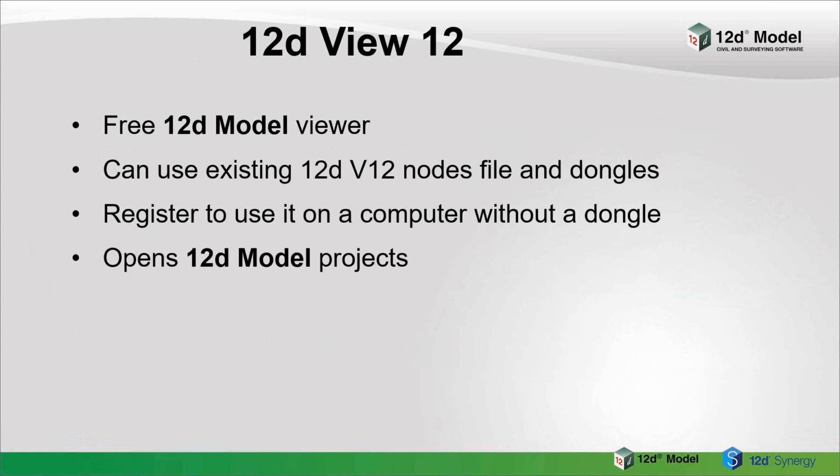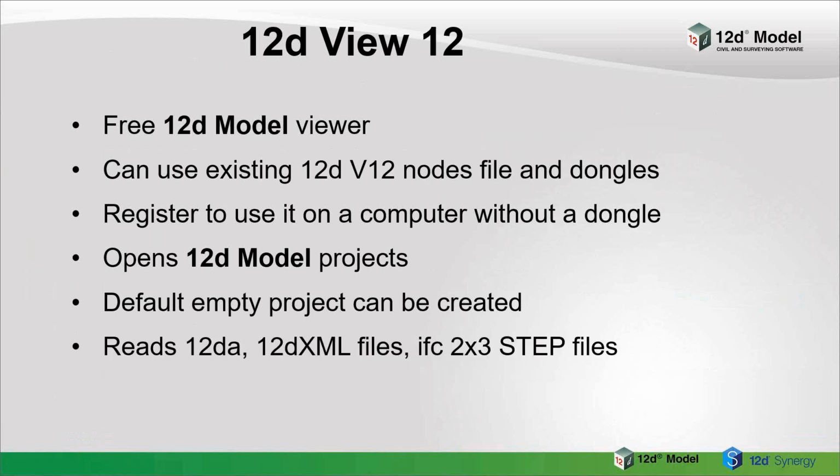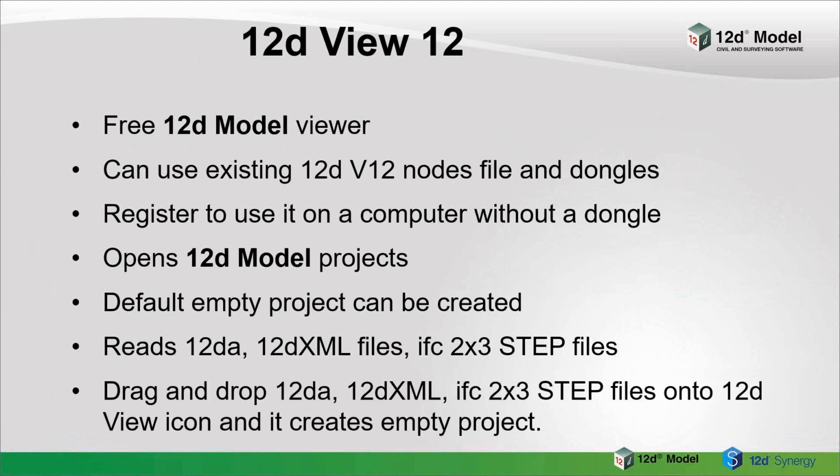It opens 12D model projects, but if you haven't had the latest C1M, you don't realise you can also create an empty project, so we can also read some data, not just 12D model projects, but we can actually read in the 12DA files, 12D XML files, and also IFC 2x3 step files. So that all can be done in the actual viewer, which is free of charge. And those particular things we read, you can also drag and drop onto the 12D View icon, and it'll create an empty project and then open up the options ready to read the data in. So actually 12D View is very, very powerful.